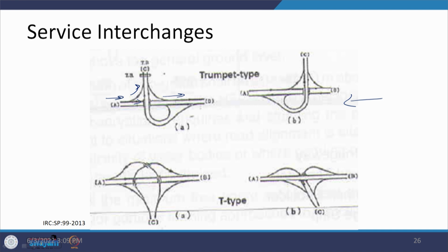So this is how it is being taken care of, and if the traffic is coming from here, then it goes in this direction, or it can go in a straight form also. Thus the through traffic as well as the turning is being taken care of. The only thing is that at this point, here or at this point, there is a grade separation, but this one is at grade. So, this is at grade, but this one is grade separation.